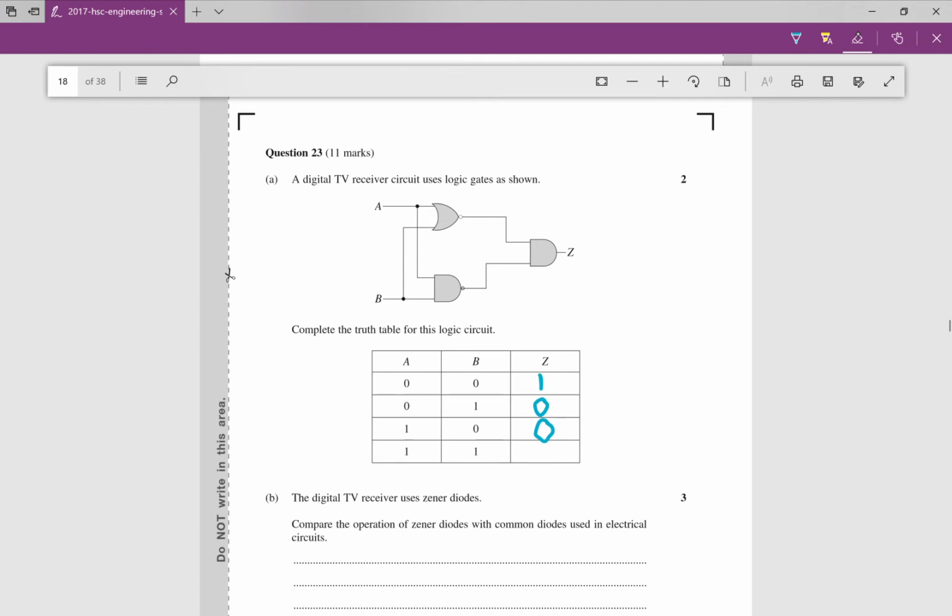So you just have to be very systematic about this and certain about what happens with each gate. And then finally we've got a 1 and a 1. So we better switch our pen back on. We've got a 1 here and a 1 here. And therefore we've got 1s arriving at all these gates. Now a 1 and a 1 means that if this was an AND gate, it would switch on, give us a 1, but we've got a NOT gate at the output, so our 1 becomes a 0.